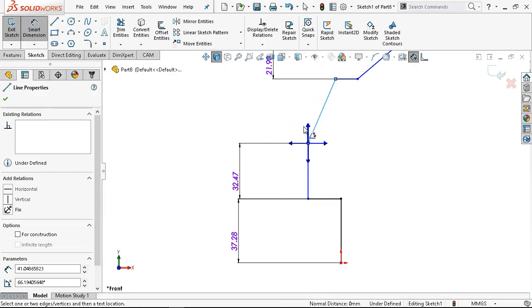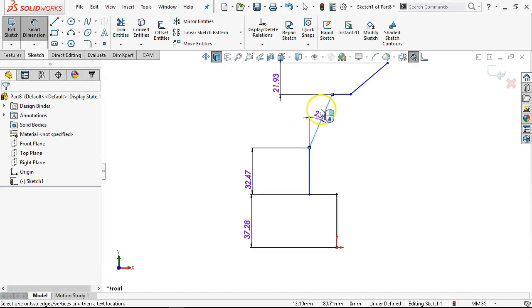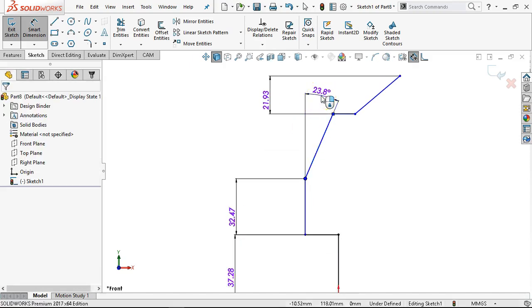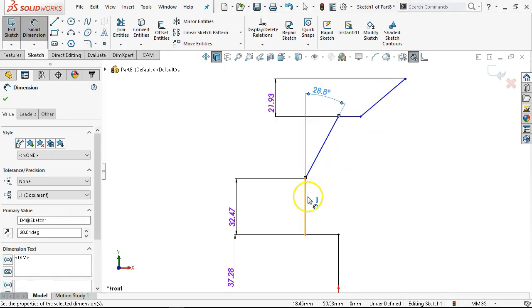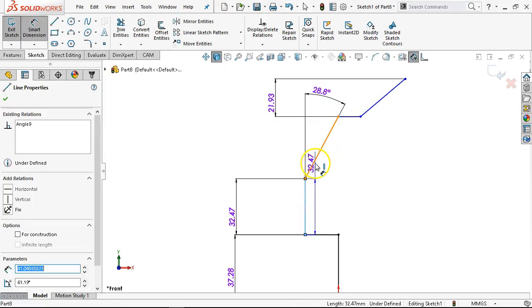All right. So the arrow endpoint to the angle. The arrow is the direction that I want my imaginary extension line for the point, and then go between, and that is 28.81. So in this case, it's probably not as effective because we have the vertical, and it would do the same thing.